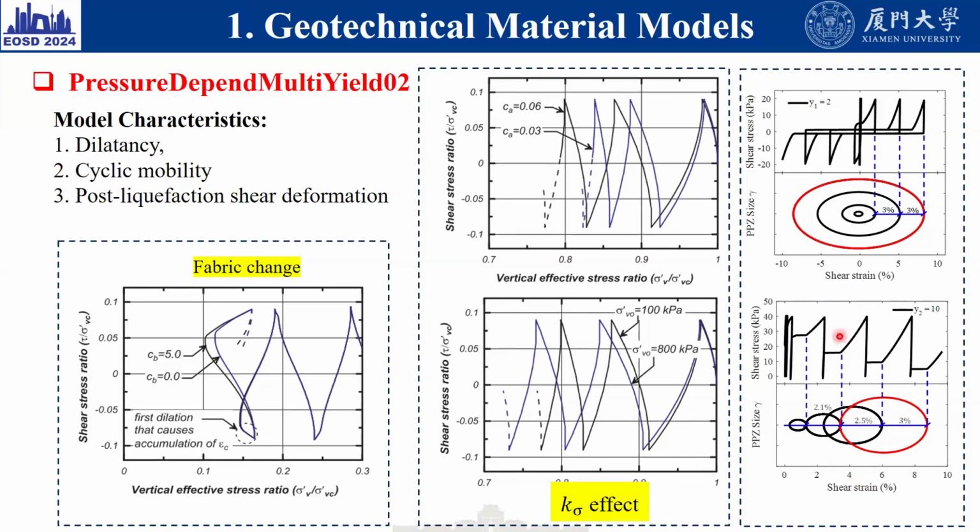So you can see this figure. We have an initial shear stress, for example maybe 20 kPa. Under this 20 kPa, you then impose the shaking. The deformation will be accumulated in a cycle-by-cycle pattern in the downslope direction. So this mechanism is very important for soil liquefaction.